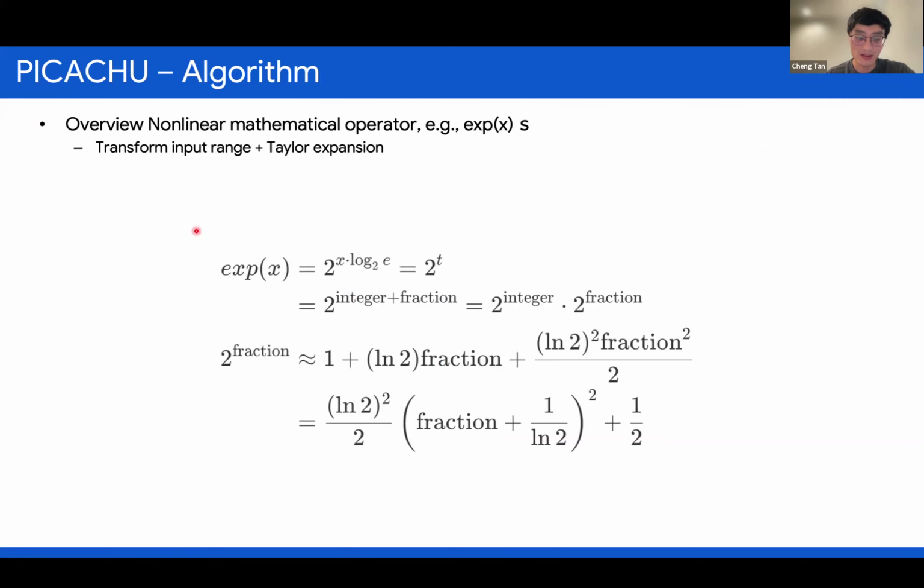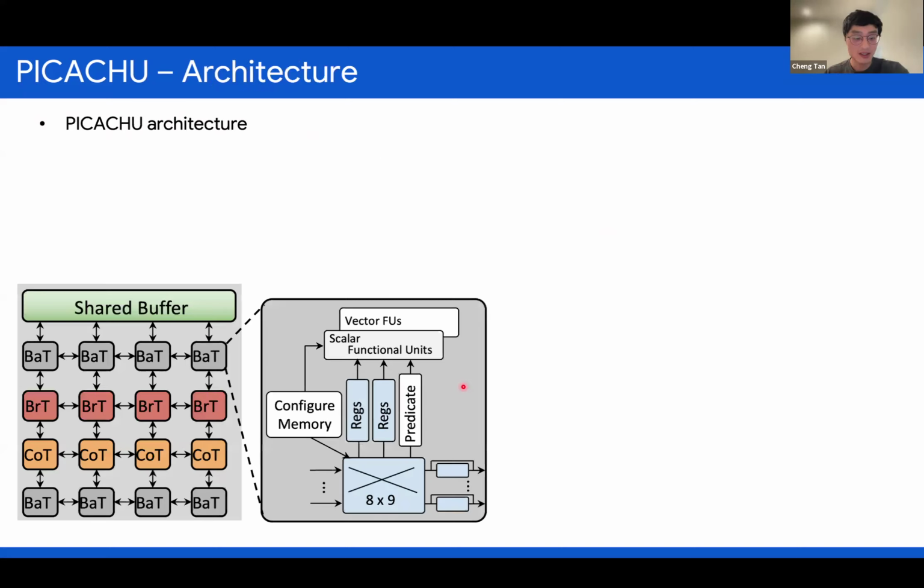Also, for the trade-off between accuracy and performance, it's well known that nowadays people leverage quantization or integer operations rather than floating point. For example, exponentiation can be replaced by integer exponentiation with Taylor expansion here. So we also leverage this in our CGRA acceleration for the nonlinear operations.